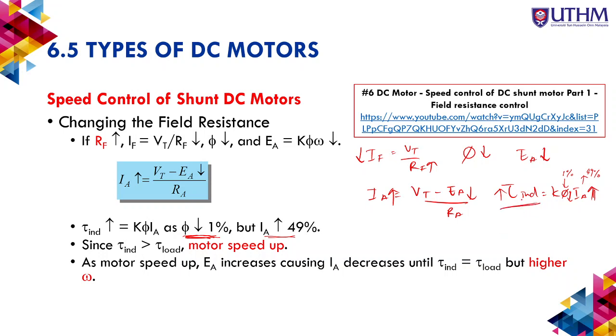So when torque increases, torque induced is more than torque load, so the motor will speed up.